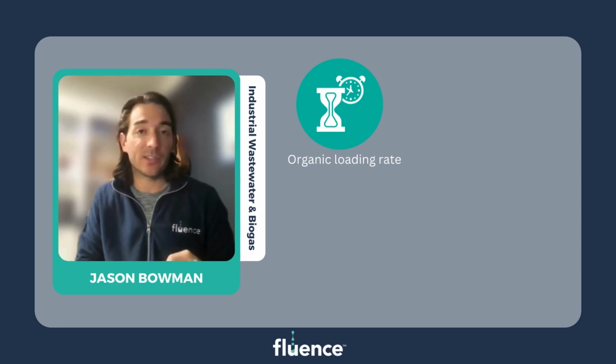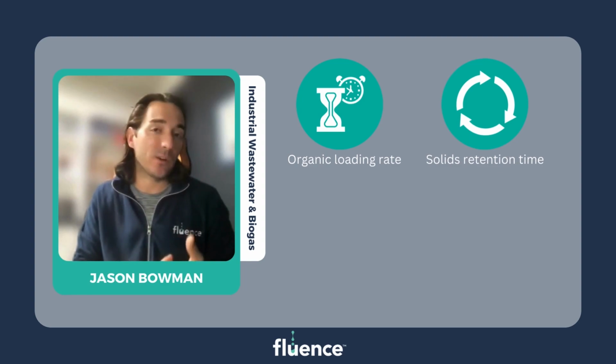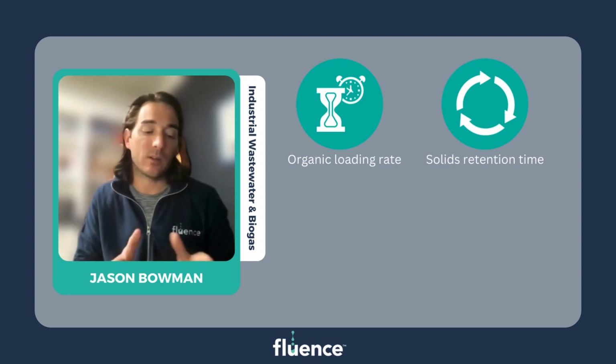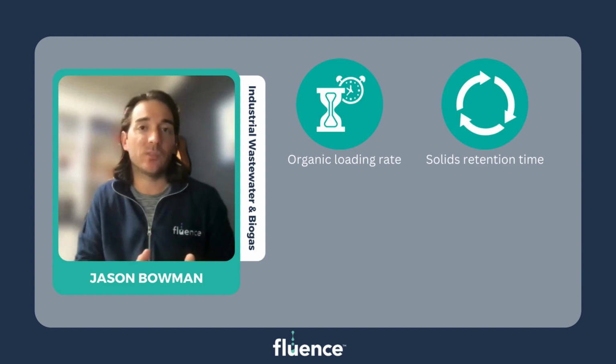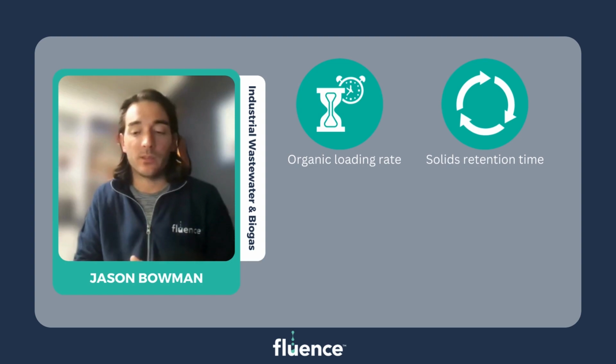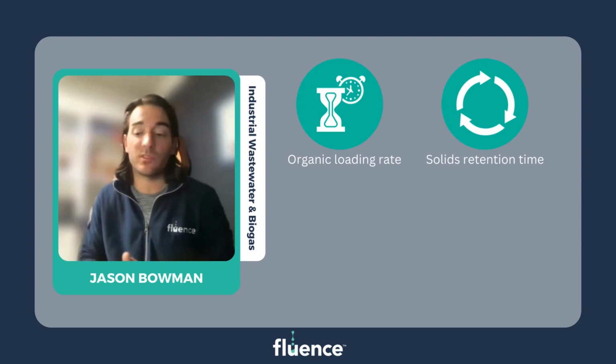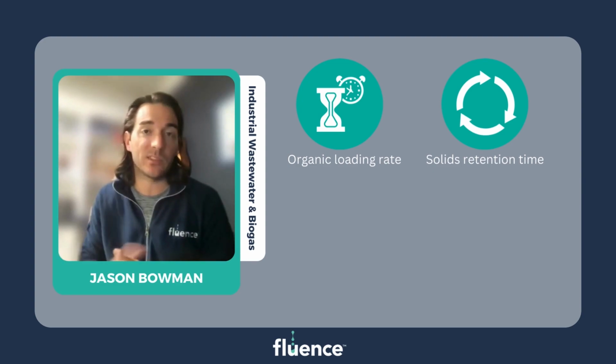The second design consideration, which is probably one of the more important design considerations, is the solids retention time. In this case, what we're saying is the bacterial solids or the volatile solids: how long are these solids retained within the reactor, how long do they have to perform the work? The way solids retention time is measured is the amount of active biomass within the reactor versus how much is being removed or wasted on a daily basis.